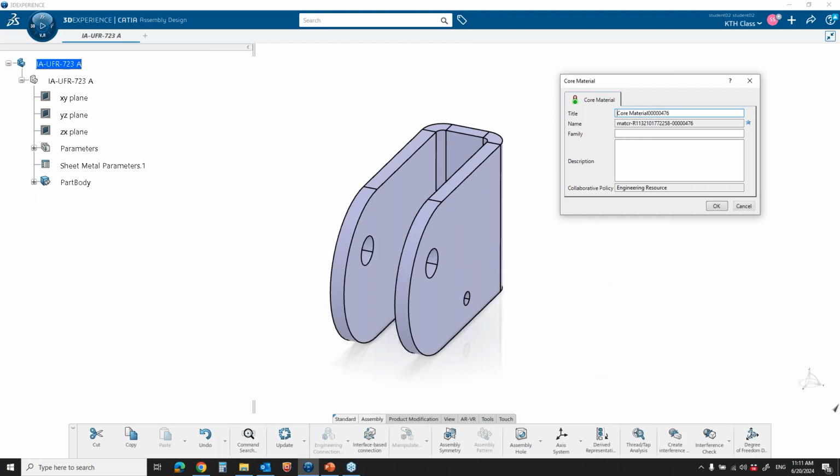Okay, now, what's changed in 3D experience as far as materials? Like in CATIA V5, you had a material catalog, material library. It's just essentially one file. And materials in V5, they serve two distinct purposes. The first being providing mechanical properties, such as Young's modulus, Poisson ratio, etc. But the second was to provide the visual properties, texture, reflection, color, etc.